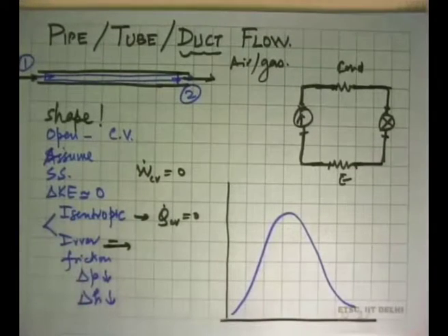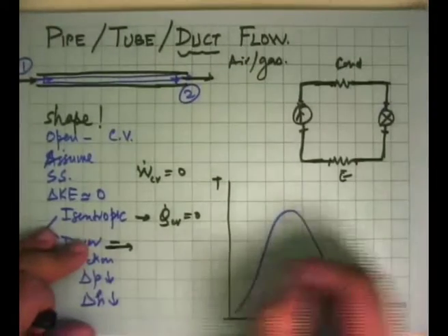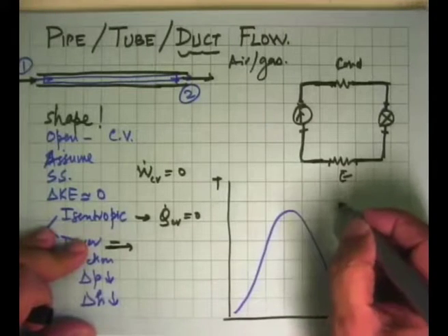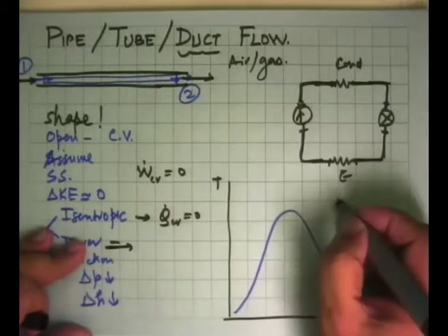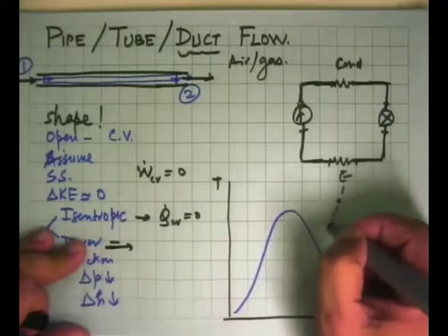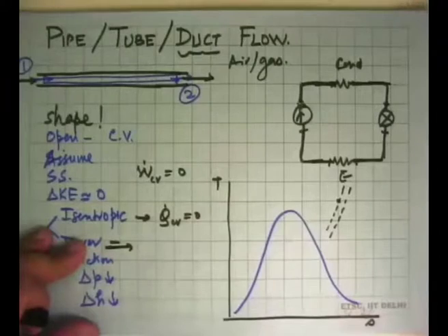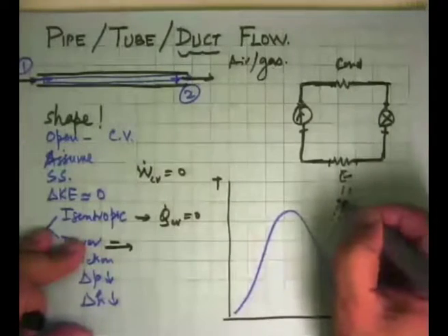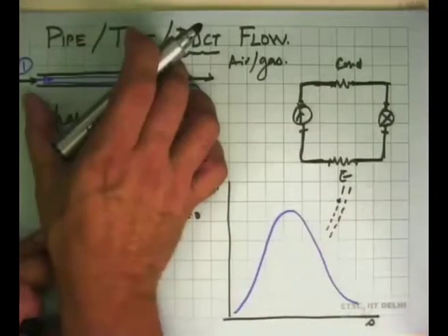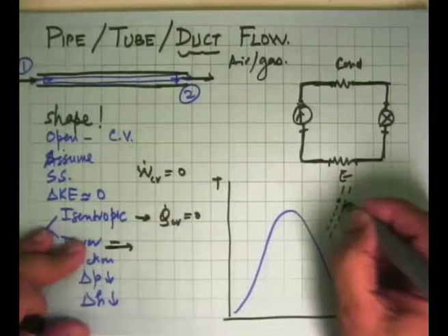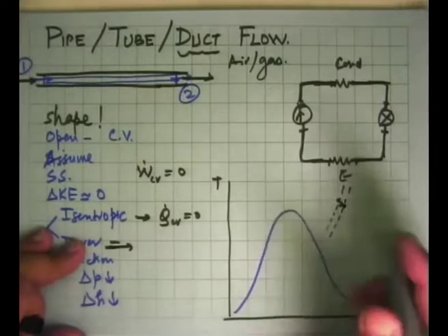if that's the thing and we are looking at a TS diagram, what we are saying is that if a flow is taking place, then the state will remain the same. But if it's a real flow, then this was the isobar through which this point was there. There will be a pressure drop, it will come here, pressure drop being an irreversible process, and since there is no heat input or output, enthalpy is remaining the same, there's sort of a throttling type of thing happening here, the state here will come down. That's what would happen in a real pipe.